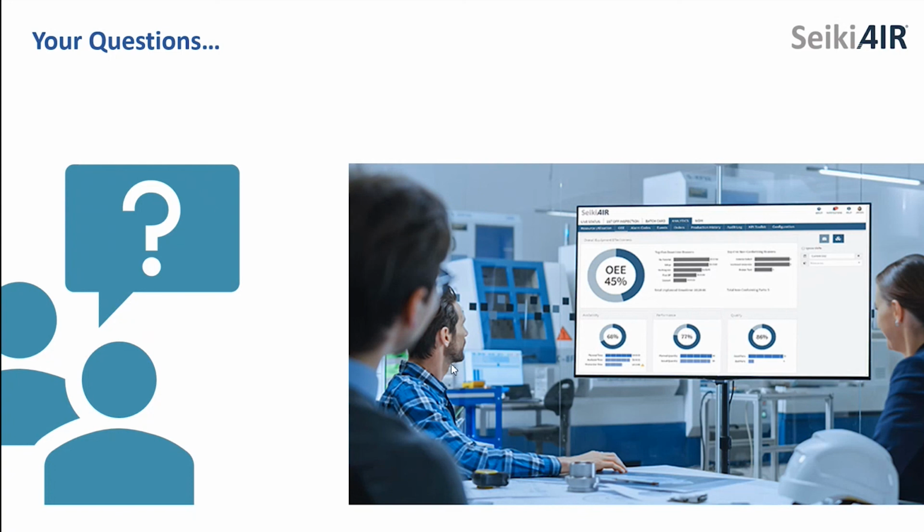Sorry, just another point. If we are talking to the machine via software, then we can get additional data. We don't pull a load of data that we really can't do anything with. But the additional data we pick up tends to be things like feed and speed override and alarm conditions. So within the running time of the machine that we're using in our OEE, you can actually see that 5% of the time my machine was running at reduced feed because the operators turned the feed override down, for example.